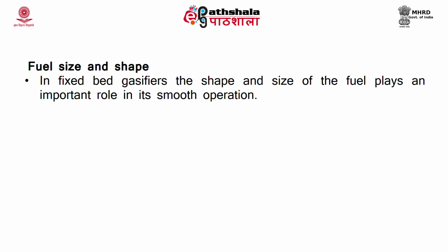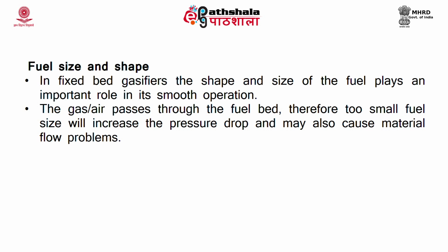In fixed bed gasifier, the shape and size of fuel plays an important role in its smooth operation. The gas or the air passes through the fuel bed, therefore, too small fuel size will increase the pressure drop and may also cause material flow problems. The bigger fuel size will not pass through the throat in downdraft gasifier with throat and may cause flow problem.